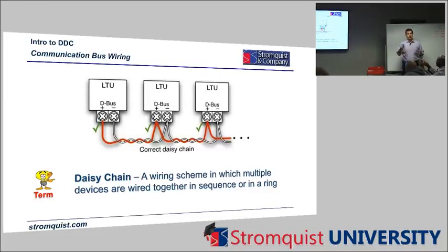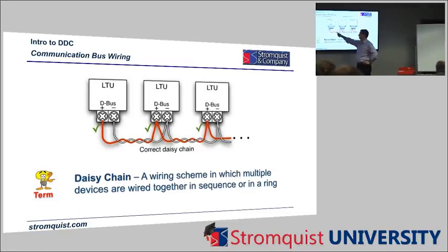What I had the hardest time understanding is that this red wire here is one wire, and this red wire here is the second wire. And what actually happens is this one goes into this terminal, and both wires get twisted together and stuck in the same terminal on that second controller. And then it continues to do that as long as your daisy chain is. Okay?